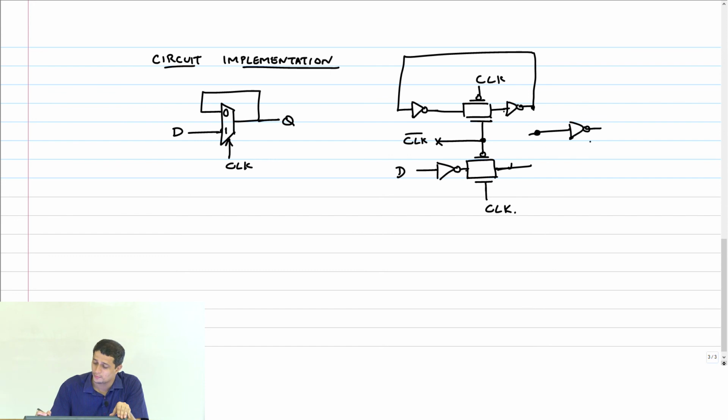No, but again, this cannot be driving here. It has to appear here. Because you can wire-OR only the outputs of a transmission gate. So I cannot connect this to the output of the inverter, because that will always be driving something, and I cannot wire-OR something there. So the wired-OR connection should always happen at the output of the transmission gates. So this is TG1, TG2. So only those outputs I can wire-OR, and the remaining.